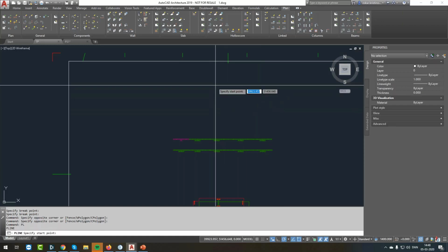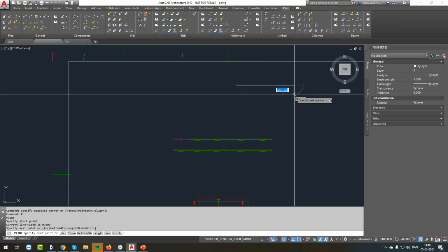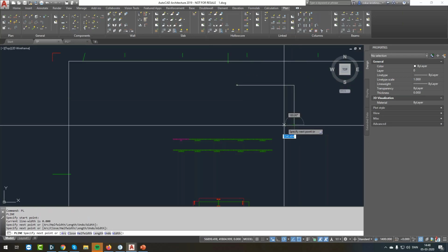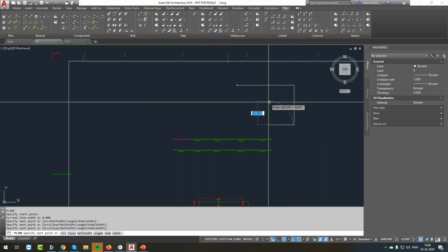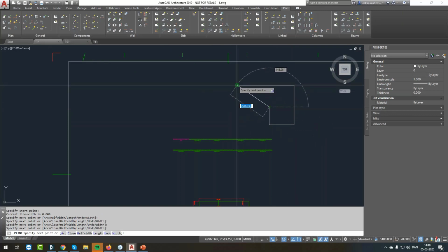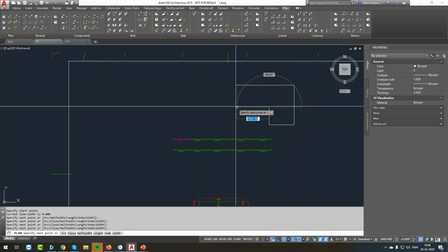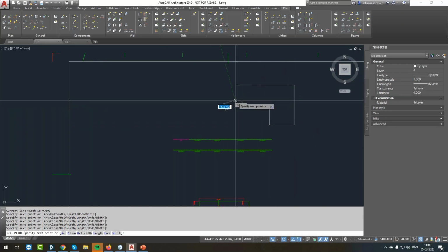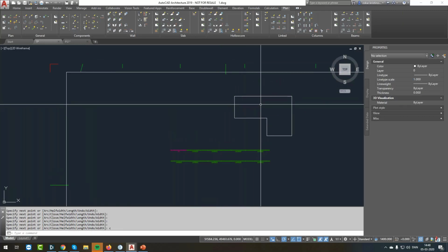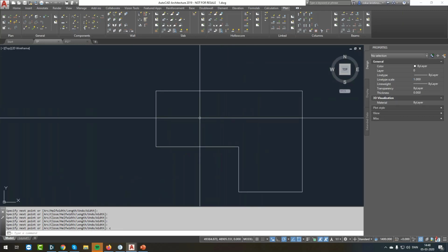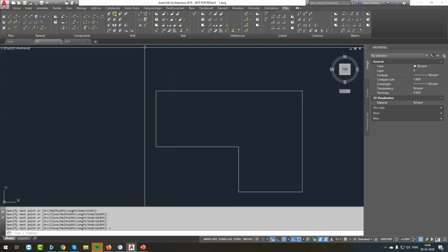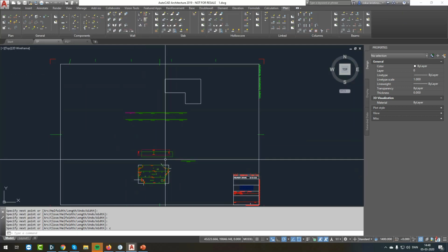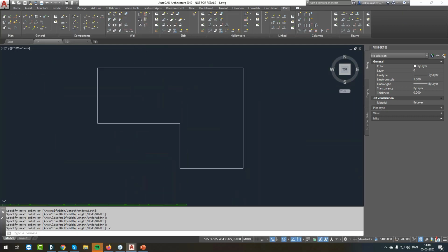So let's say that we have some walls in this particular shape around here with the outline. Then instead of drawing the walls like we normally do in Impact, we can use the new function up here called draw wall outline and base the walls on the polylines, just like Oskar did on the slabs down here.